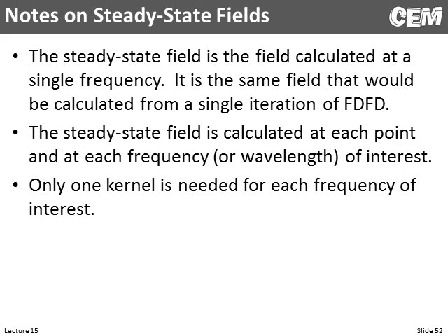A benefit of finite difference time domain, though, is in that duration of one simulation. We can actually Fourier transform at many frequencies and get the field over many frequencies from just one simulation. That's very unique.